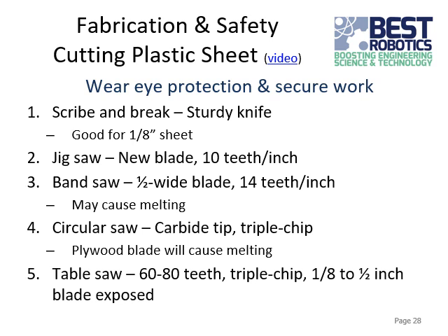Just go slow with it. The recommended teeth per inch is 10, but you can see the blades will sometimes say if they're good for cutting plastic. Again, you want to make sure that your workpiece is really well supported. Otherwise, the jigsaw may break pieces off.